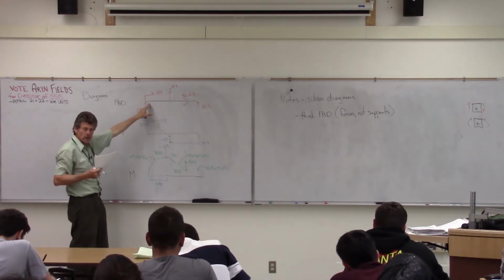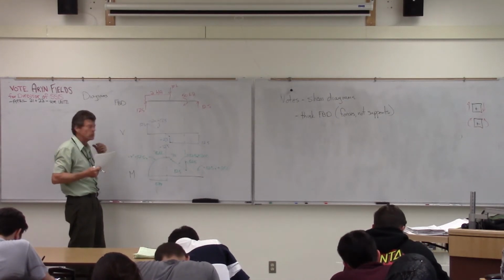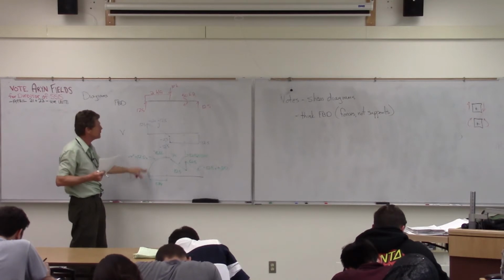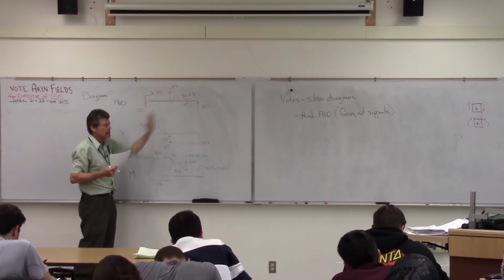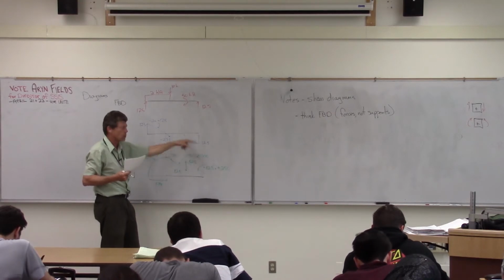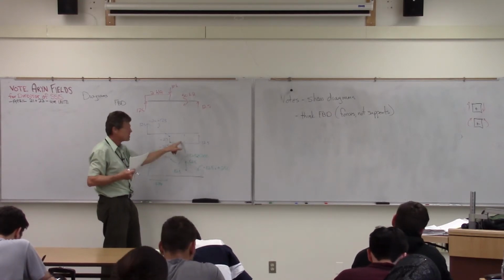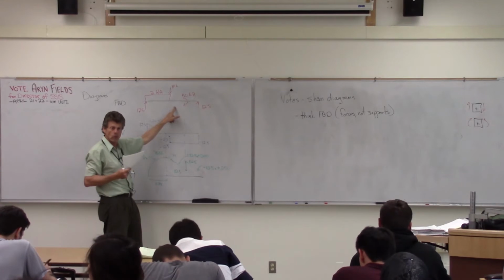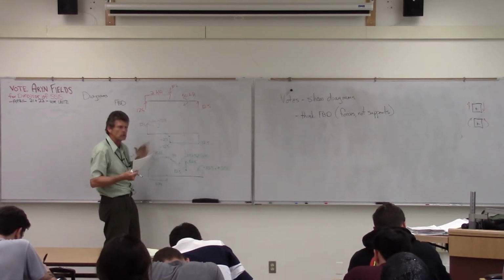If it was a fixed connection there would be a concentrated twist there too, which would show up in my moment diagram there. But again, anytime there's a support, we should expect to see a jump, whether the support's on the end or it's in the middle. Because again, what is support doing? We substitute it with a concentrated force.